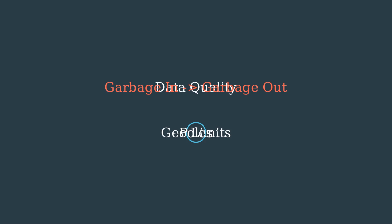Okay. And maybe the most obvious one, data quality. The output is only as good as the input. If your initial street center point or the orientation angle is wrong, your parking rectangles will be in the wrong place or pointing the wrong way. Garbage in, garbage out. Always the case with data. And finally, using accurate constants is important. Getting the values for the Earth's radii of curvature right, usually from that WGS84 model, affects the precision of the meter to degree conversion. Little details, but they add up.